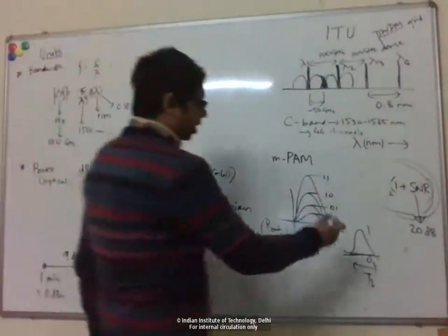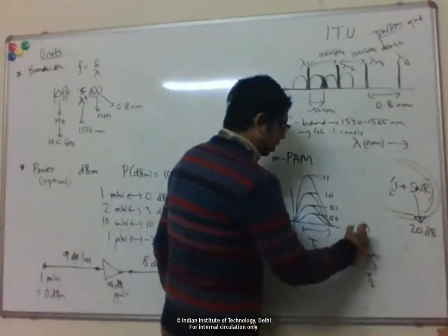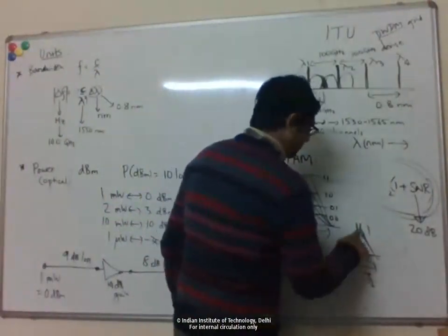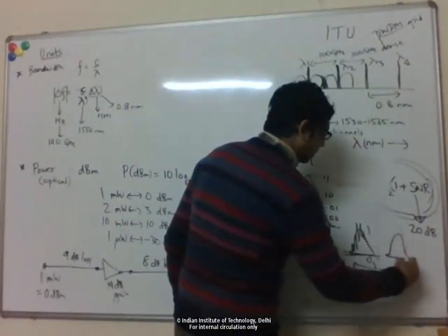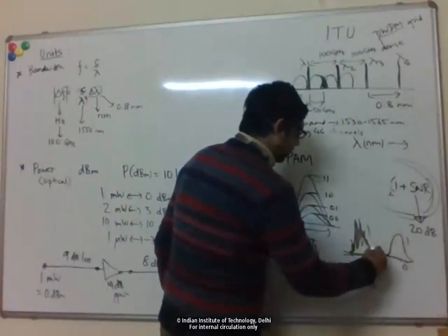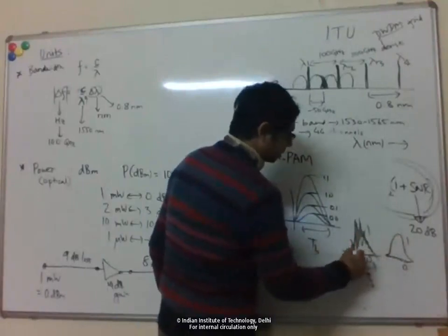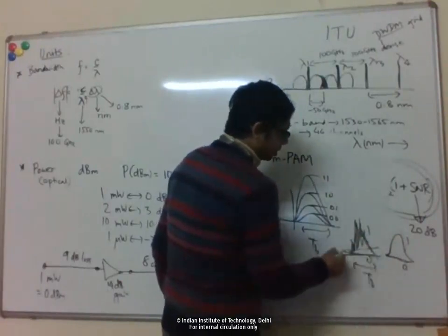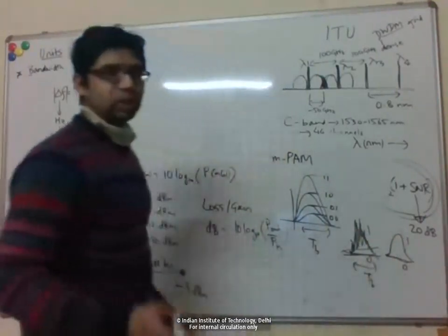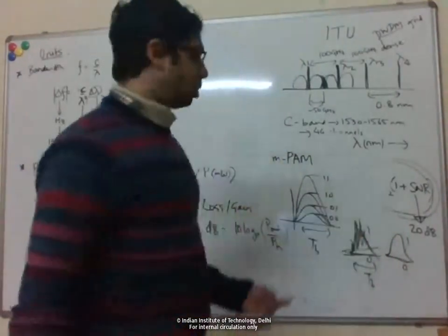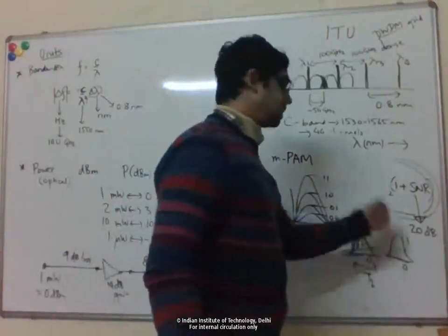And it's independent of the SNR. You have some noise on this, you can see. A high SNR means the noise is very small, and 1 and 0 are well separated. A large amount of noise means that the separation becomes lower. But as long as the SNR is more than 1, I can always distinguish between 0 and 1, and you don't really gain by increasing the SNR.